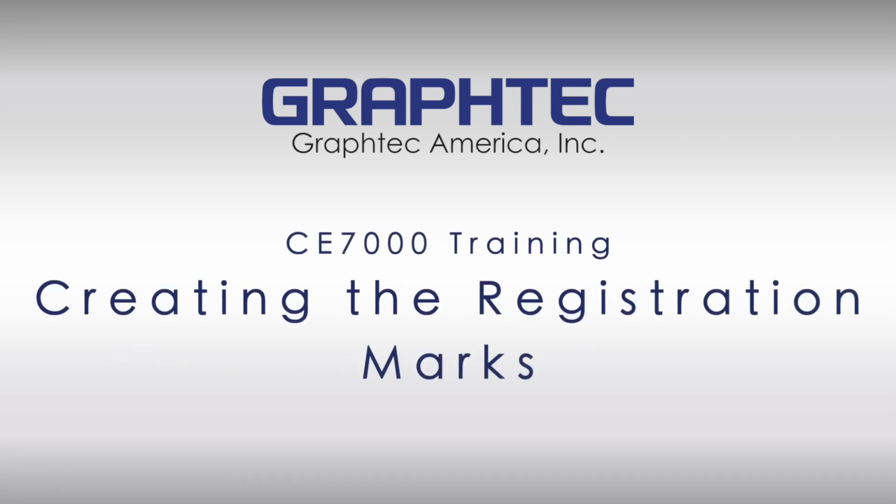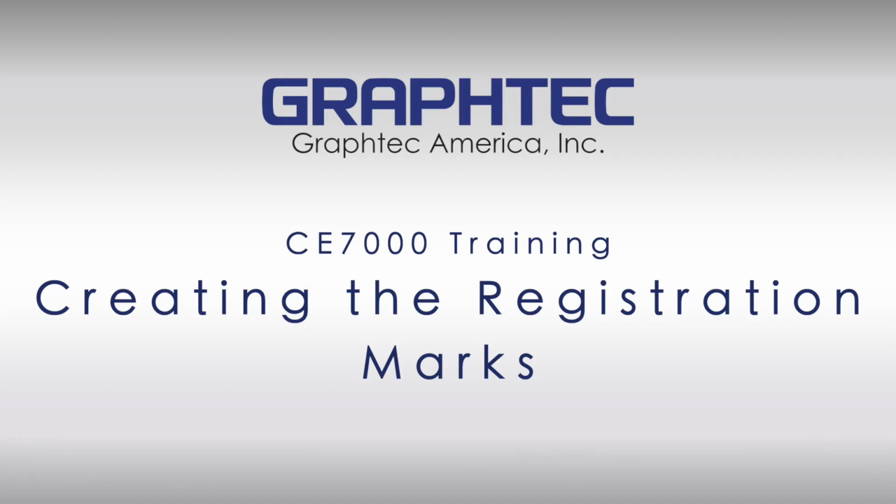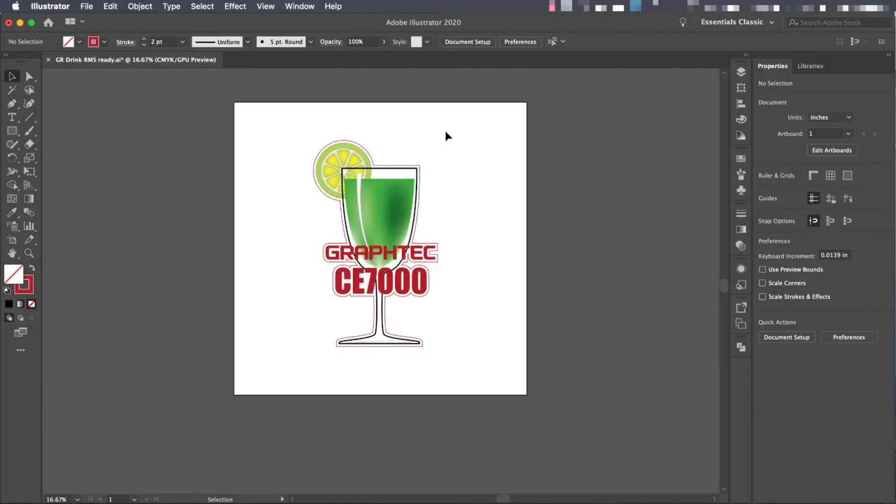In this part of the print and cut segment, we will cover how to create registration marks using Cutting Master 4. While we will be using Adobe Illustrator with the Cutting Master 4 plugin, the steps are generally the same with CorelDRAW and with Graphtec Studio applications. If you use a different application, the steps are likely the same, but it is best to check your software manual. You'll notice that we already have the cut line established here.